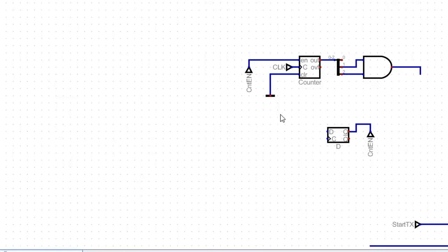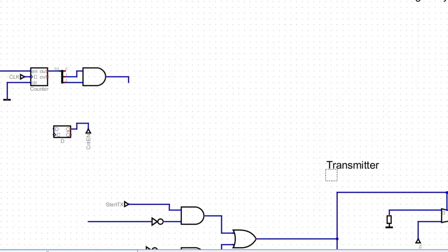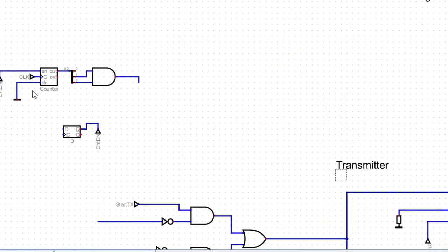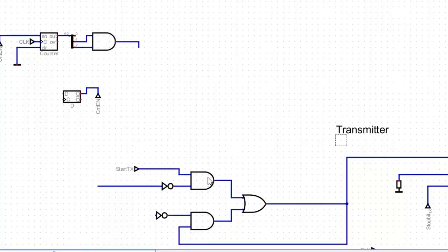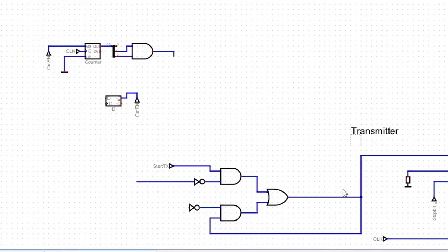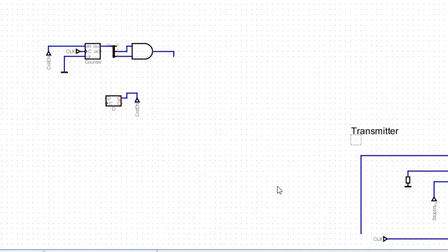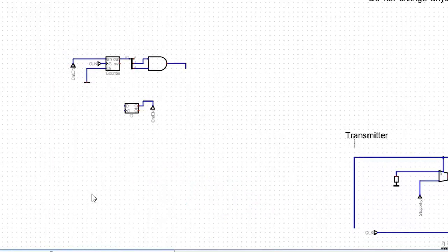What is missing in your state machine? A state machine is made up of output logic, a state rememberer, a memory thing, and then a next state logic. What is missing? Okay. Yes, that's your next state logic. So that next state logic there, which for some reason is driving into the multiplexer select line, you need to take this out. So just Control X that whole sum of products piece of logic, and make it feed into your flip-flop.